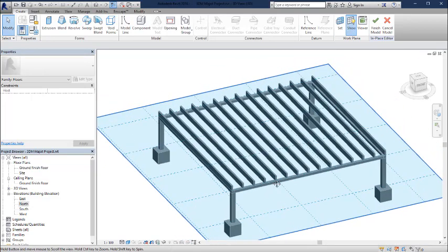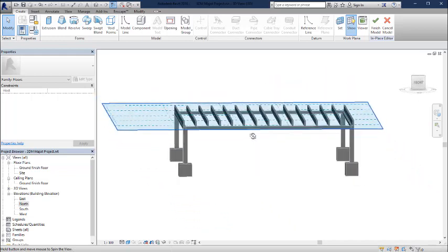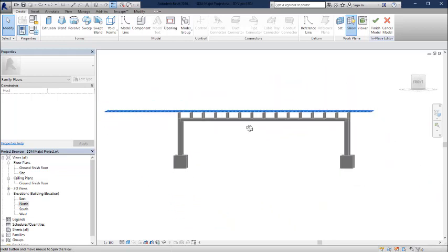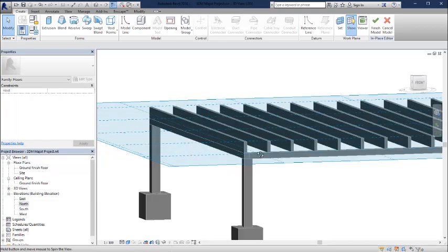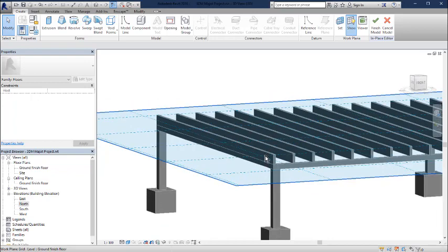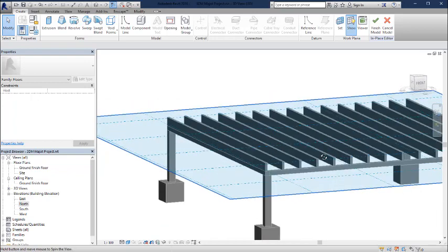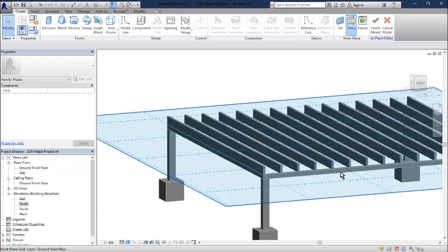So of course if we're going to have a side view like that, it's going to be hard to draw on top of this work plane, and you can kind of imagine the work plane as a sheet of paper. So you would actually need to change this work plane to a vertical work plane before drawing in another axis.